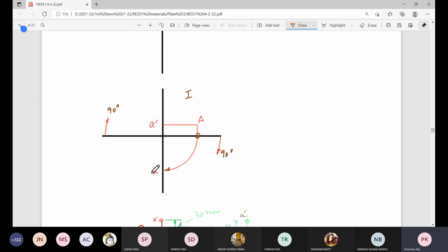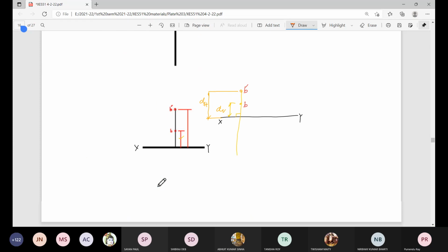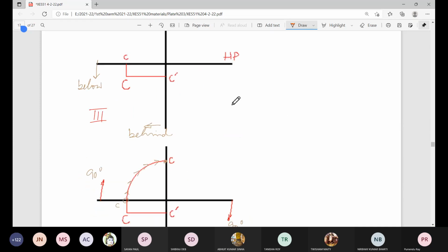So this difference is there for first angle and third angle, which are normally accepted. For India, Russia, and many European countries, we follow first angle projection, and United States and some other followers use the third angle projection. Now for third angle projection, it is essential that you are the observer here.